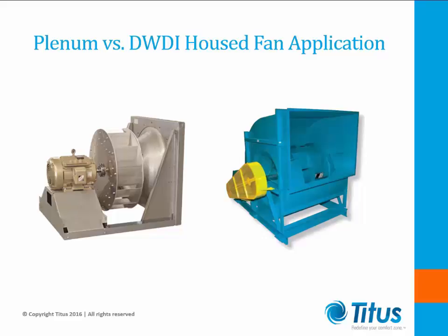Housed fans in blow-through positions will also require an air diffuser, which decreases the efficiency further. The combination of these two system effects brings even the best housed double-wide fan efficiency to or below that of the Plenum fan, thereby eliminating the benefit of a fan scroll. With regards to noise, Plenum fans have the benefit of effectively utilizing the entire unit as a fan housing, which offers superior attenuation. The system factors that decrease the housed fan's efficiencies discussed above also increase the noise level of